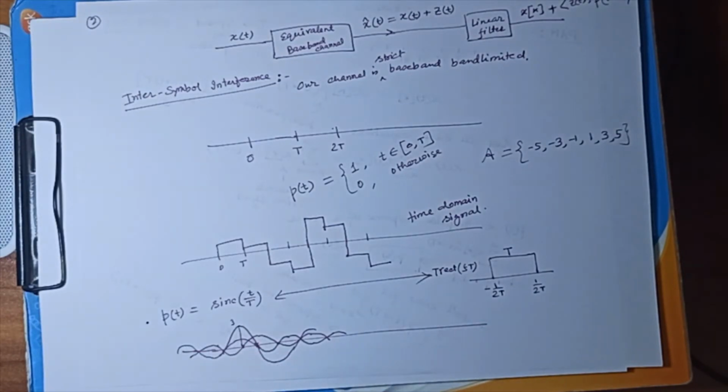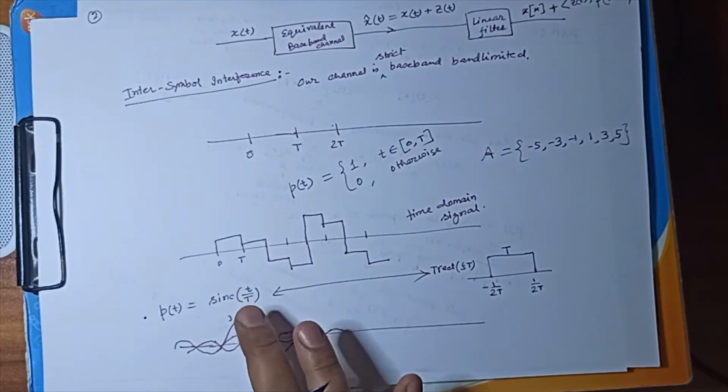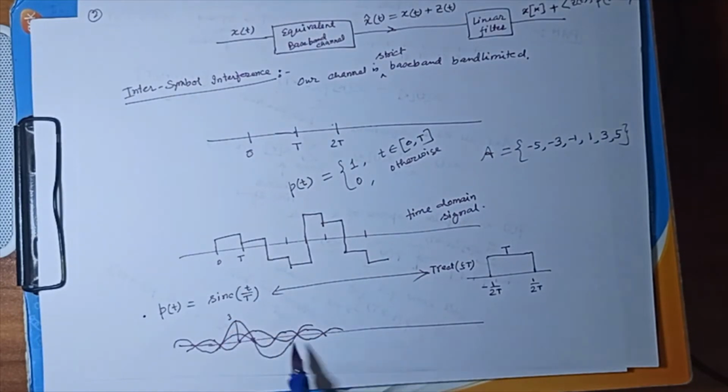That is not the only issue. There are more issues, because one issue is that the sinc is not a causal filter. Because this goes from minus infinity to infinity, you have to wait for the entirety to get even one sinc. So this is not a causal filter. To get a real causal filter, you have to basically truncate it. You cannot really realize an exact low pass filter. There will be some roll off, right? That is one problem, of course. So you have to truncate it.